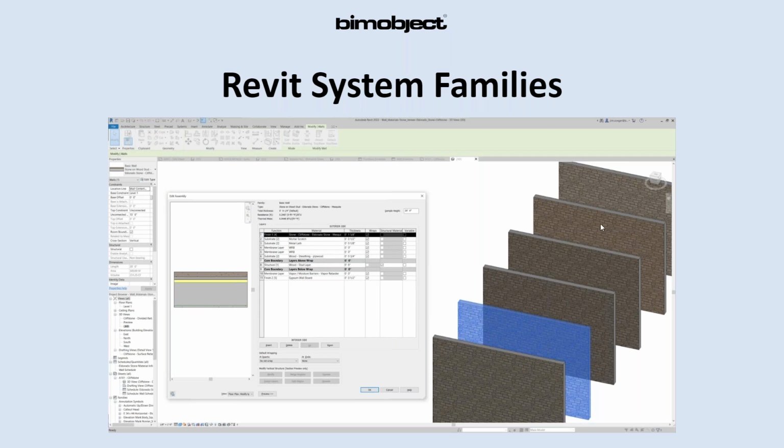So it's not just, in this case, I believe this is Eldorado Stone. It's not just Eldorado Stone. They are the top one here. However, there is also mortar scratch, lathe, you got sheathing, plywood, stud layers, insulation, vapor moisture barriers, and gypsum wallboard. And if they were going to paint, the interior is on the bottom, the exterior is on the top, they would put a paint, like a Sherwin-Williams paint in there. So that would make up the Revit system family.